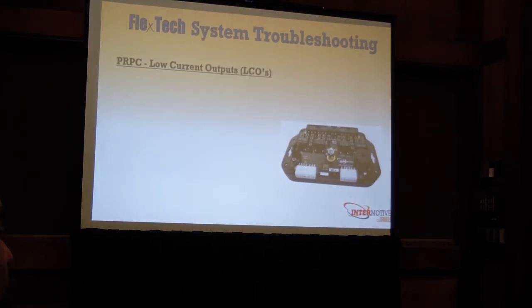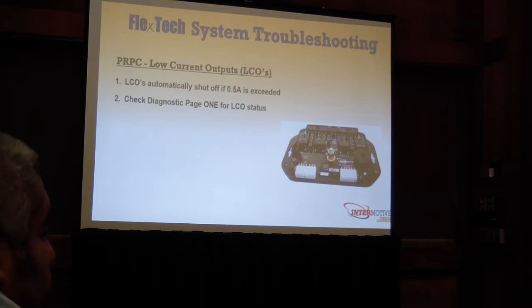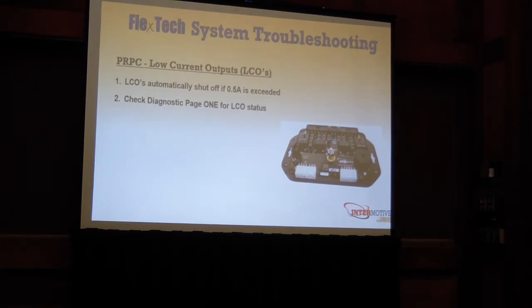Talk about the low current outputs. These outputs are smart FETs, and they have over-temperature and over-current protection, so they'll automatically shut off to protect themselves.